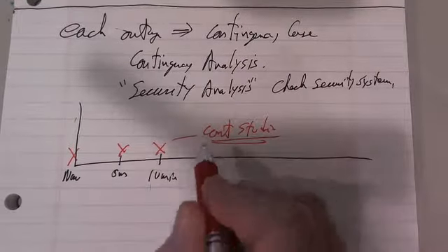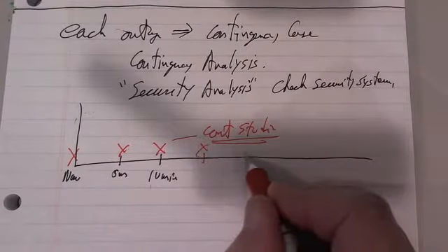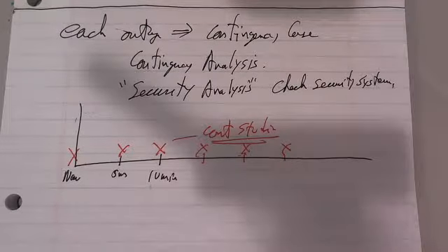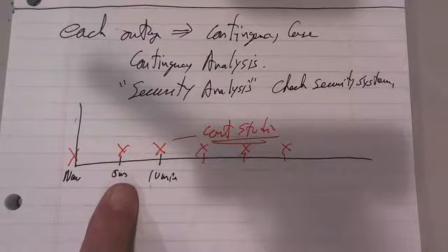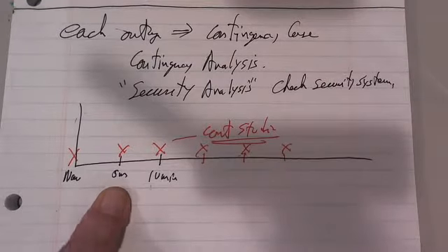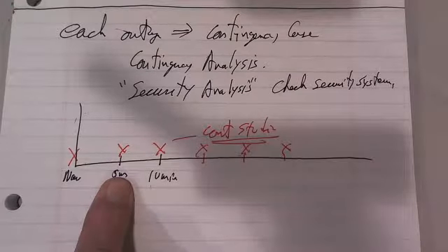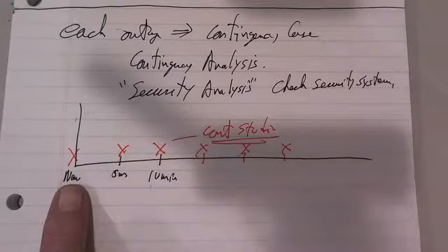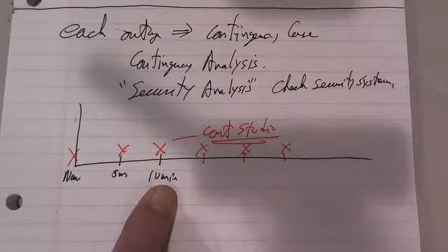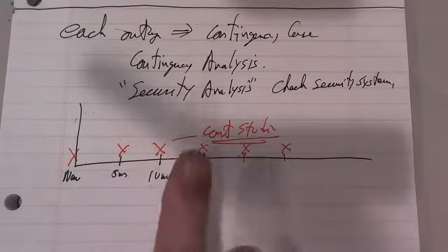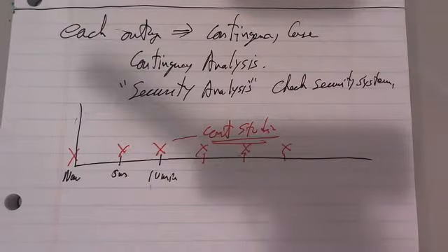Every 5 minutes, depending on the power of your computers, you keep running it. And why do you have to keep running it like that? I mean, why run it 5 minutes later? The reason is that the load may have changed or flows shifted for some reason. And if you've put a new generator on, the system is in constant change. So you want to rerun this contingency analysis over and over again.